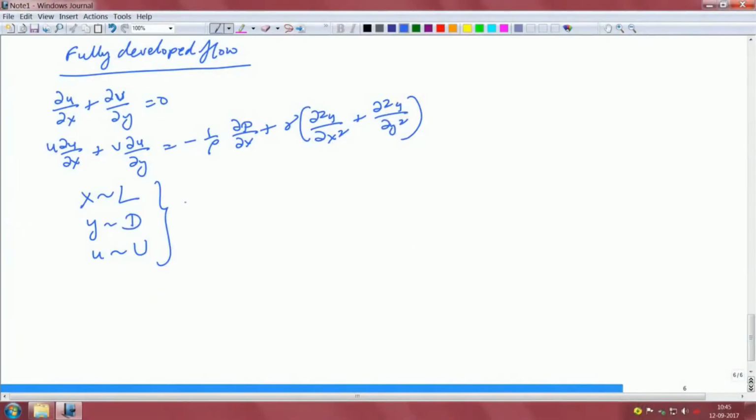because we saw it is only 1.5 times the maximum velocity. So, the scale is still the same. Okay. We are not going up by one order. Okay. So, of course, using this from the continuity equation, you have u by L should be the same as v by d, right. This gives rise to v being equal to u times d by L, where L is much greater than d, correct. So, when L is much greater than d, you can take v to be almost equal to 0 in this particular case.